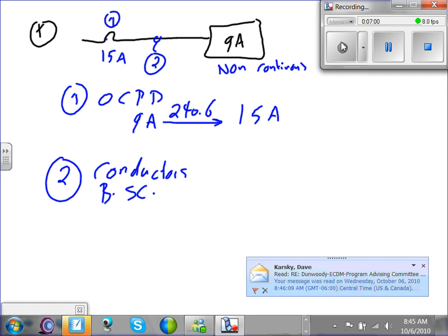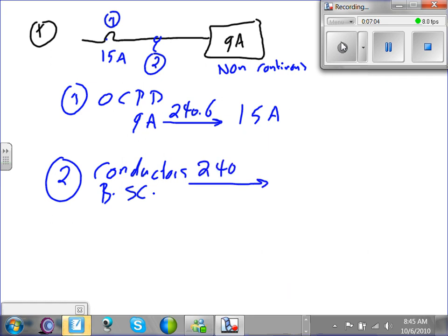Okay, so I have a conductor, branch circuits, the technical term, wire, if you want to call it. So from here, you're going to take it to table 240, oops, not 240. You're going to take this one to which table? 310.16, soon to be 310.15(B)(16), right? Table 310.16. Which column? Whom am I going to pick? Ryan, which column are we going to go to? Look at the amps. Your options are 60, 75, or 90. Column meaning the installation. 60.